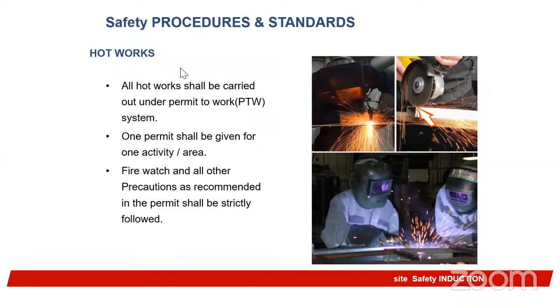Every procedure that you want to establish or put in place, you should make sure that everything is communicated to the person you are inducting, especially if you are inducting a welder. If you are inducting generally everybody who is just coming to work on the site, you might talk about working around someone who is welding, not carrying flammable materials around someone who is welding. If you observe something, maybe sparks moving around, all these flashes, all these welding fumes, going to maybe where there is a hot wall, where there are flammable materials, you can call their attention.